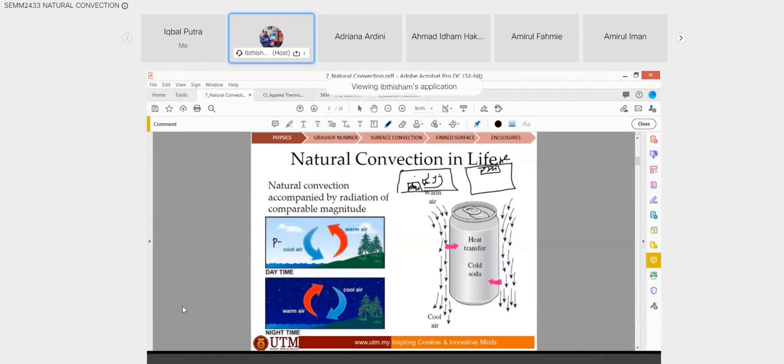And in an air conditioning system, the air is cold. Because the density is higher than this one, the air will go down. So imagine if you put an AC below and the heater on top, you wouldn't achieve the objective that you want. You cannot cool the room, you will cool only this region, not the whole room, because the density of the air is high, so you are trying to cool only the bottom region.